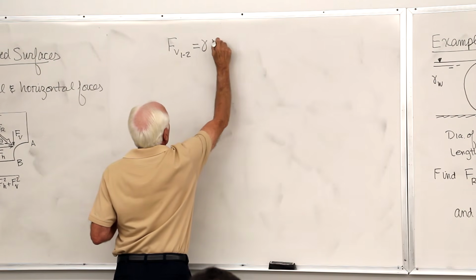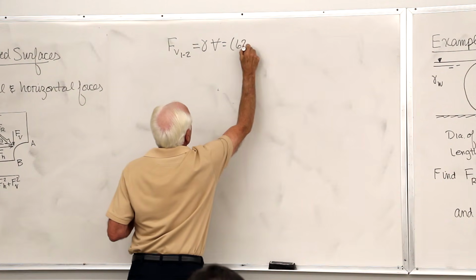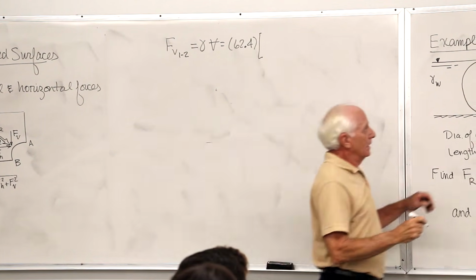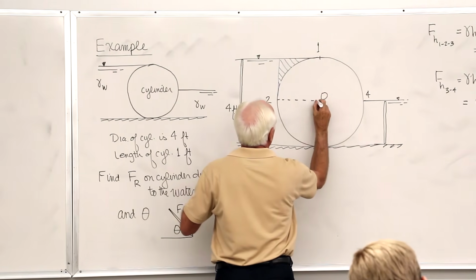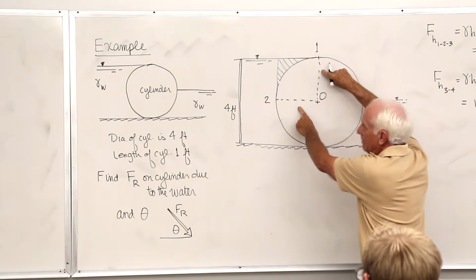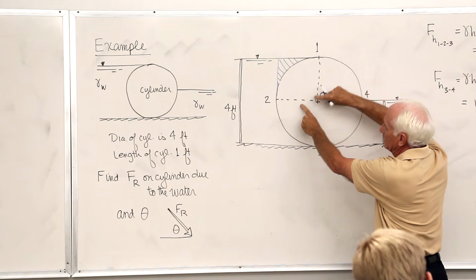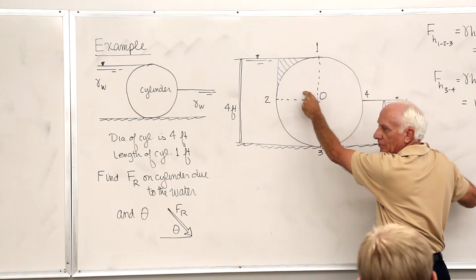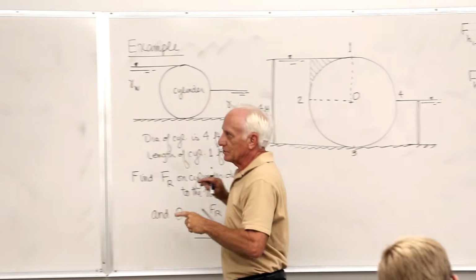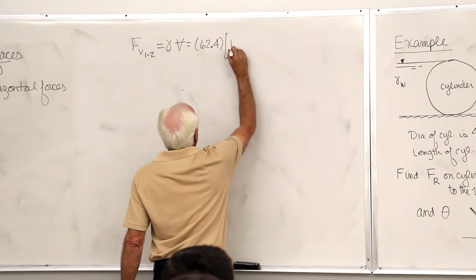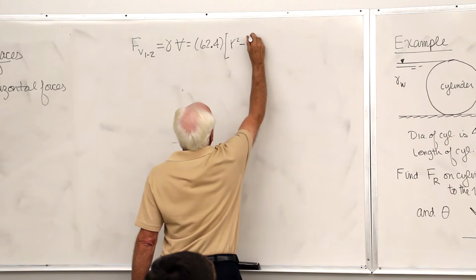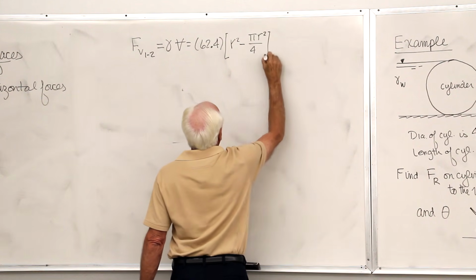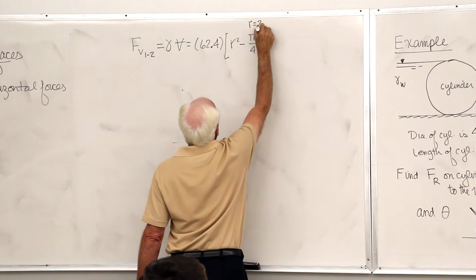Gamma times the volume. Okay, the volume. Take that square, 2 feet on a side, 2 by 2. Square. Subtract off a quarter of a circle, 1/4 pi r squared. So a square, R squared, radius squared, minus pi r squared divided by 4. R equal 2.